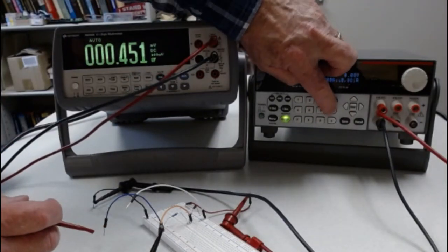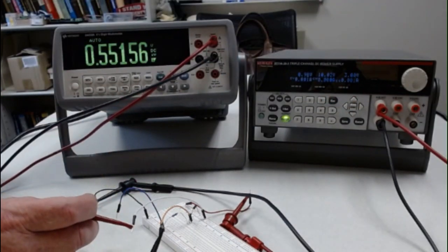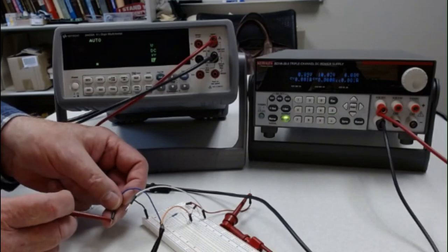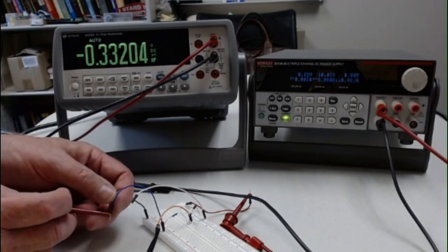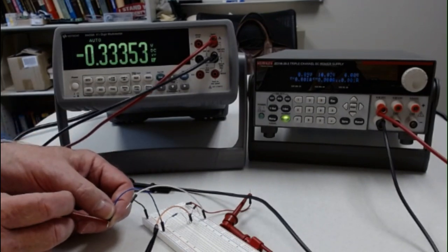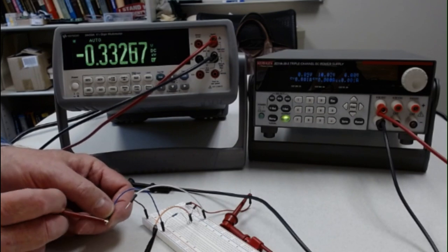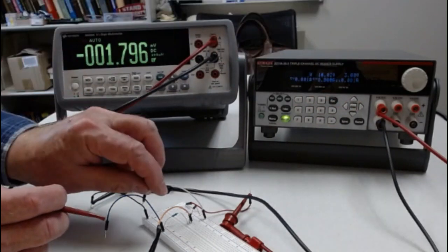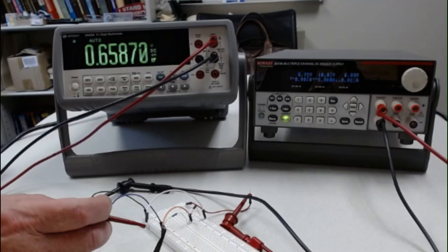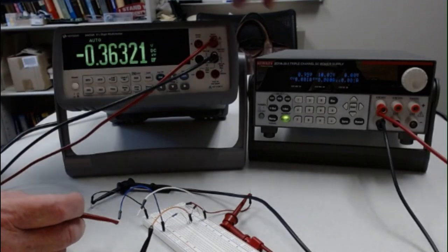0.9. Diode, resistor. It's in this area that the change is starting to occur, that you're going to see it going from a low resistance to high, from low current to high current, and it takes off and it goes to low resistance. So this is in this range, right in there. You'll see it if you graph it. Okay, now we're going to go in 1 volt increments. So we're going to go to 1.0, enter. 1 volt. Voltage across the diode. Voltage across the resistor. Again, ignore the minus sign.